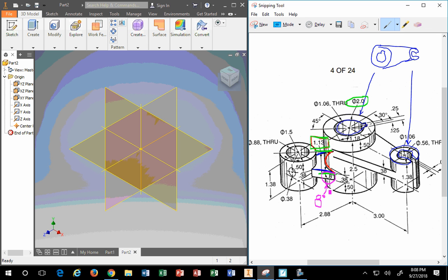It angles in, if that word makes more sense. It angles in 8 degrees. It tapers. Technically, I'd call it a taper. It tapers in 8 degrees. So it's really neat. Very difficult to look at, though. And the students have asked in the past, well, okay, if it does that, why don't I have the distance of it on this side? I'm like, it doesn't need it. So no, you don't have the linear distance. It just goes in 8 degrees.